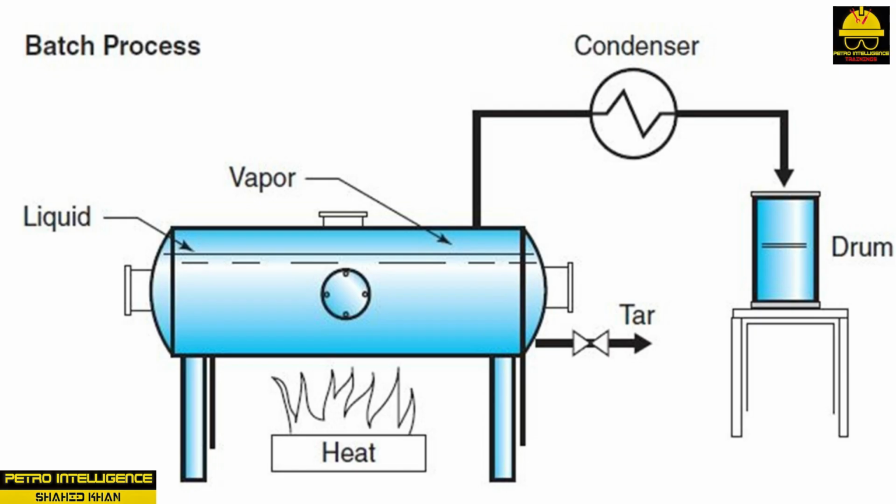The distillation process traces its roots through three distinct operations: batch, continuous batch, and modern fractional distillation. Batch distillation, as shown in the picture, is the oldest distillation process. The raw materials were mixed together and charged to the still. During phase 1 of the distillation process, heat was added to bring the mixture to a boil. The overhead vapors were condensed and stored as final product.